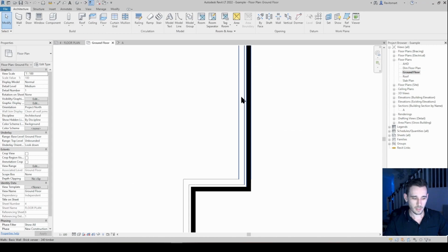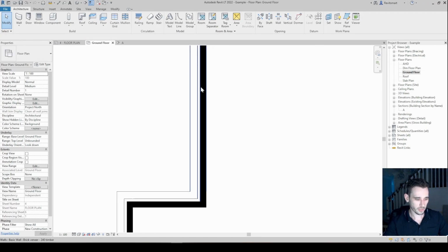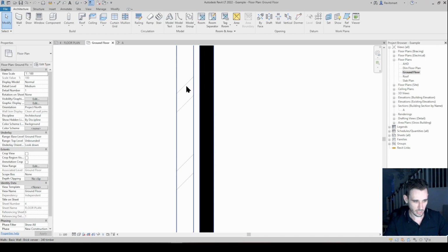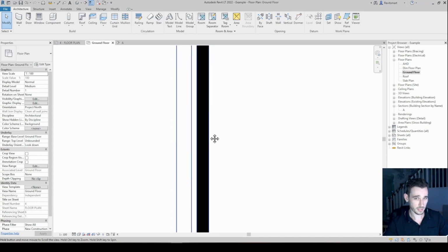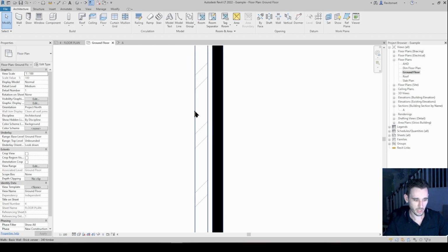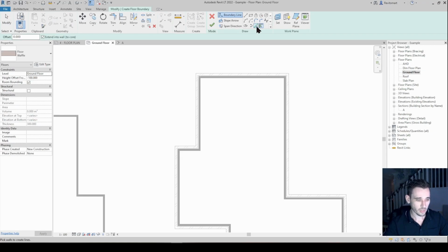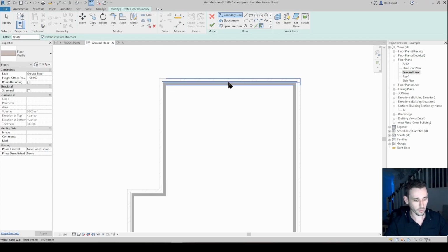They're a bit trickier when it comes to brick veneer walls. Which line of this wall do you think the slab would need to be drawn to? Would it be drawn to the outside of the brick, or the inside of the brick, or the inside of the wall, or where do you reckon? Have a think. The correct answer is going to be, notice where it says the core of the wall.